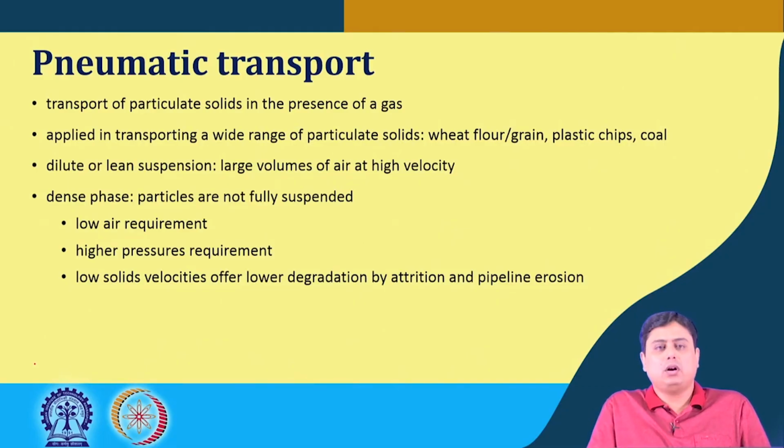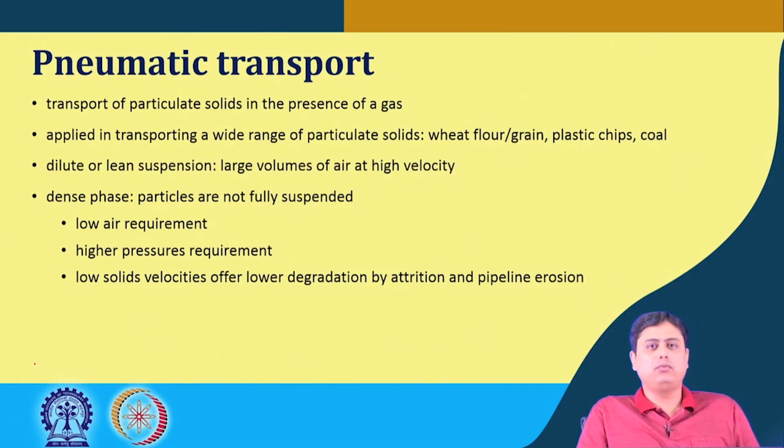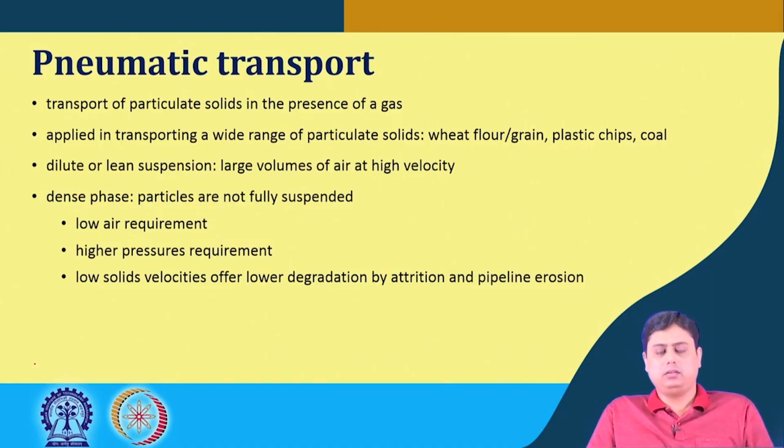Now in case of dilute phase, we require a huge volume of air at a very high velocity to take these fine particles, or the particulate solids, from one place to the other. In case of dense phase transport, the particles are not fully suspended, or rather, all the particles in fact are not in suspension.